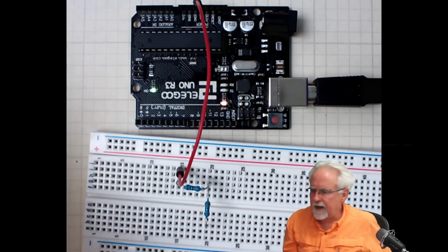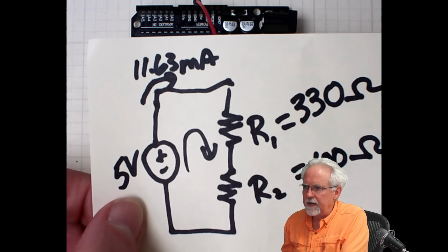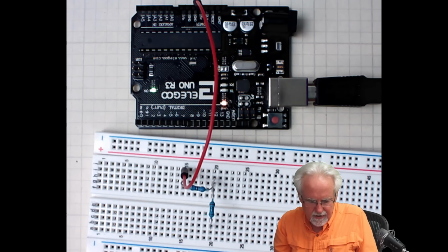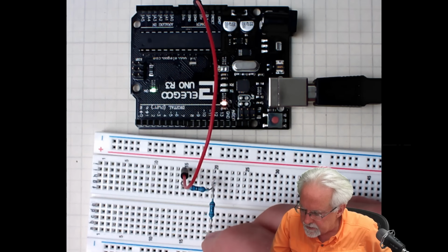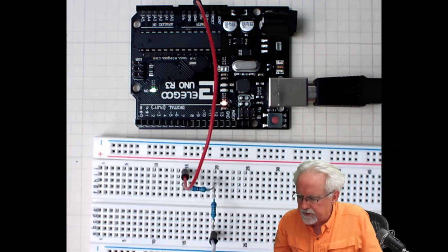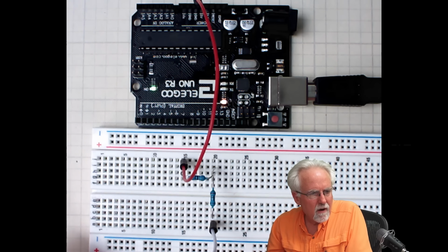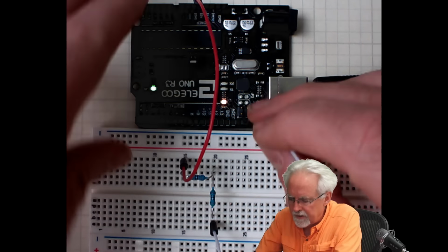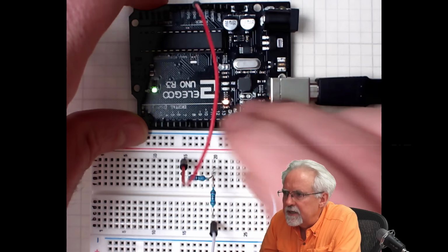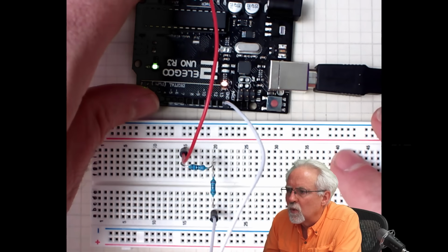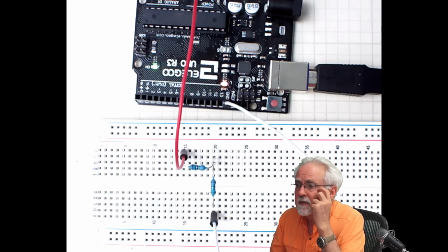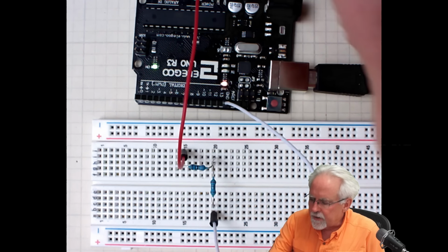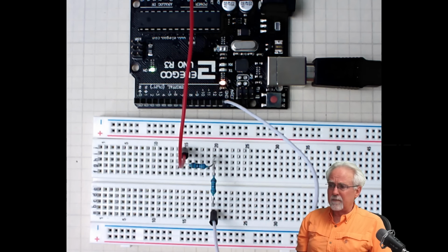And so now I have made this circuit, right? Wrong. What am I forgetting? I have to take this column, the bottom of the resistor, that bottom of that R2, that bottom of that 100 ohm resistor, and I have to connect it back to what? Back to the negative, which is the GND, right? The GND is right next to pin 13.